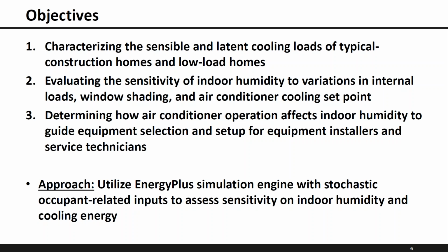And then we're also going to investigate how certain controls of the air conditioner impact humidity, and what kind of guidance can we provide to installers and technicians to design the equipment and set up the equipment to mitigate potential humidity issues. So our approach was to utilize the EnergyPlus simulation engine with stochastic related inputs to model the internal gains and the window shading.